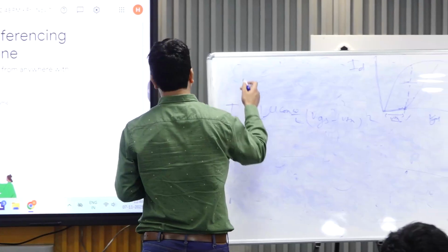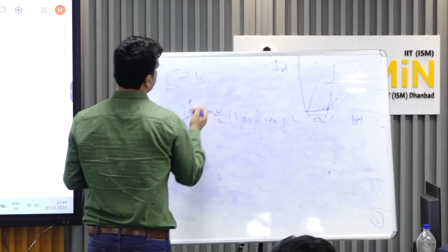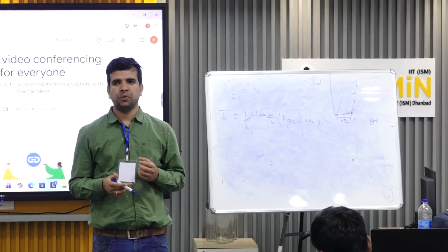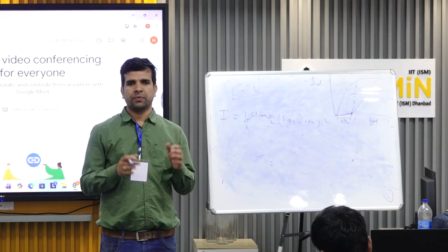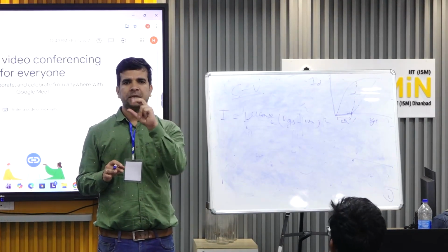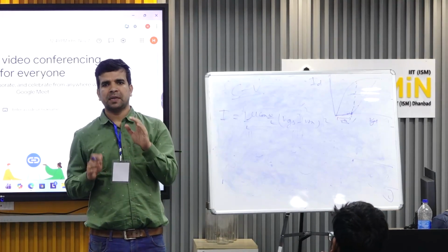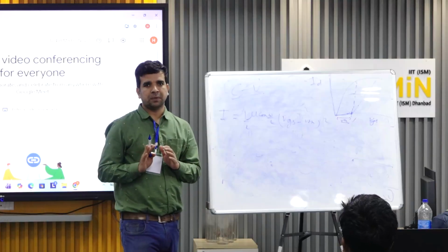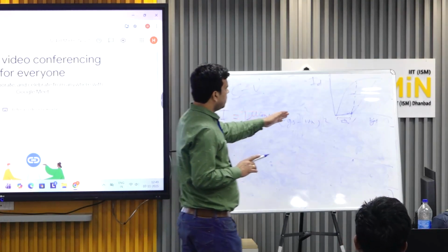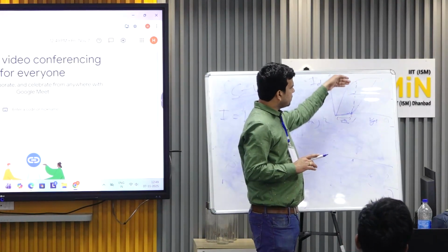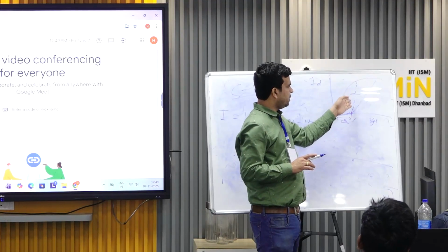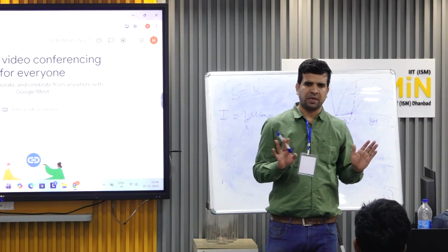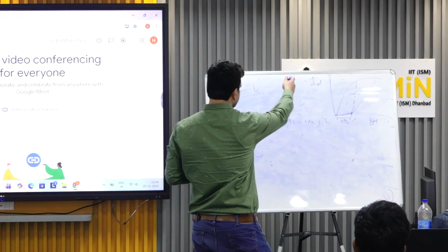So this is using ID-VG, but the best accuracy for the threshold voltage will come if you do it with a CV measurement, capacitance versus voltage. Some advanced features you can also find out this way. You can make any capacitor and do the CV, capacitance versus voltage. If you don't have this feature for CV, then it's fine. You can do the ID-VG characteristics, in log or linear scale, and you can find the threshold voltage. Not a problem, totally fine.